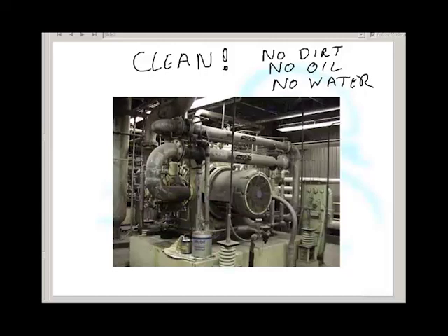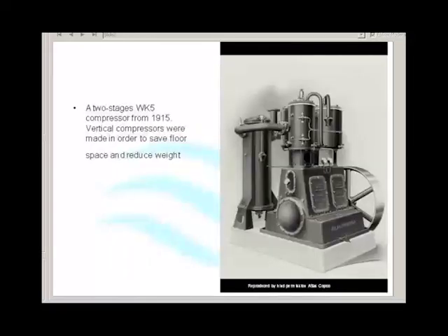Now, some of you may already work on sites where you are dealing with compressed air, and in a lot of places, it's absolutely terrible. It's full of dirt, it's full of oil, and it's full of water. If that's the case, you're going to have problems with your pneumatics. Now let's have a look at a few compressors so as you become familiar with them.